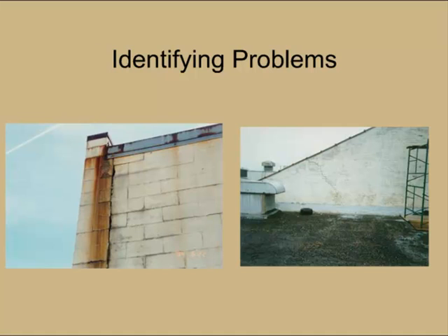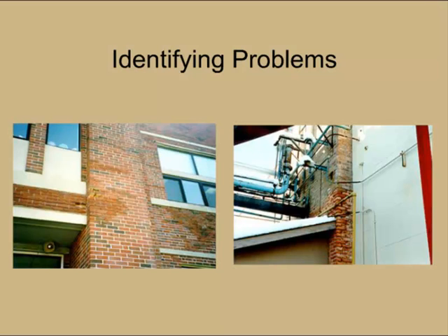A couple of examples of movement-related. On the right-hand picture, you can see there's a diagonal crack there. That's called stair-step cracking, and that's typically indicative of movement of that wall trying to flex and the masonry resisting it. And the left-hand picture, that large vertical crack there you see, generally indicates thermal expansion of a wall, but the corners being restrained by a stiff column element. And here we got just a couple examples of deteriorated mortar exposing the edges of the brick.